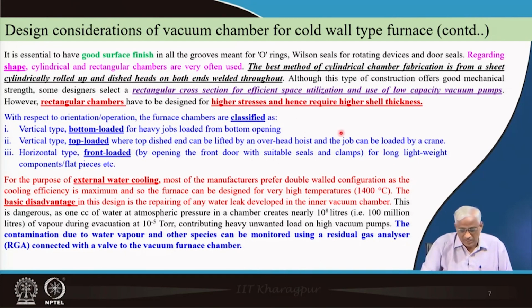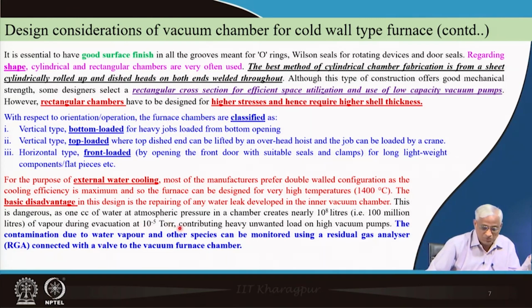Similarly, if you go to 1400 degrees centigrade, you have to take care of the water cooling circuits, and the budget has to be worked out. At 10 power minus 5 torr, you have to be very careful. I have told you this yesterday also, and earlier also.